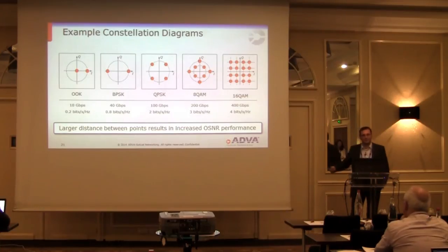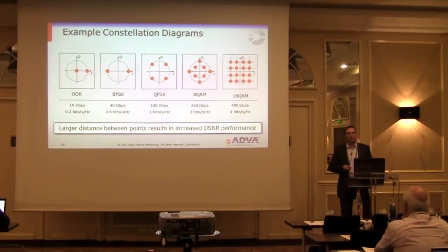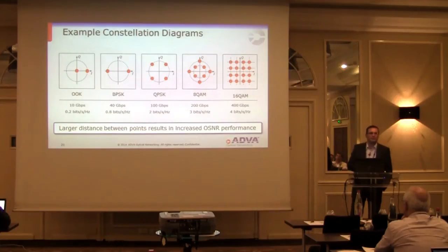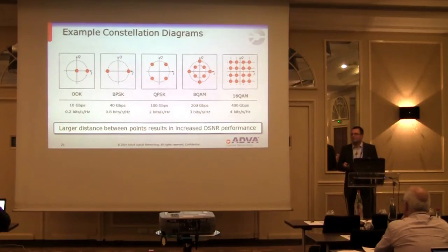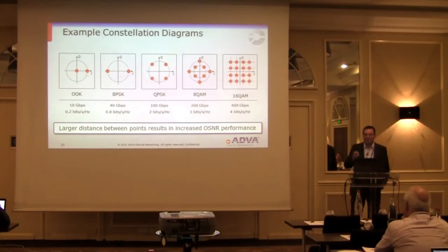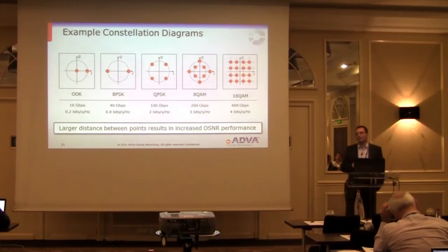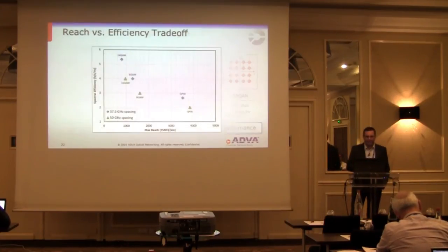And of course, the wavelengths and all the other stuff we do. And we can go on. So there's not only 16 QAM, there is 256 QAM, there's 1024, 2048 QAM in radio technology today. So at some point, we will see this in optics as well. Today, capacities are so high that these techniques are a little bit difficult to build because of all the signal processing we need for that.